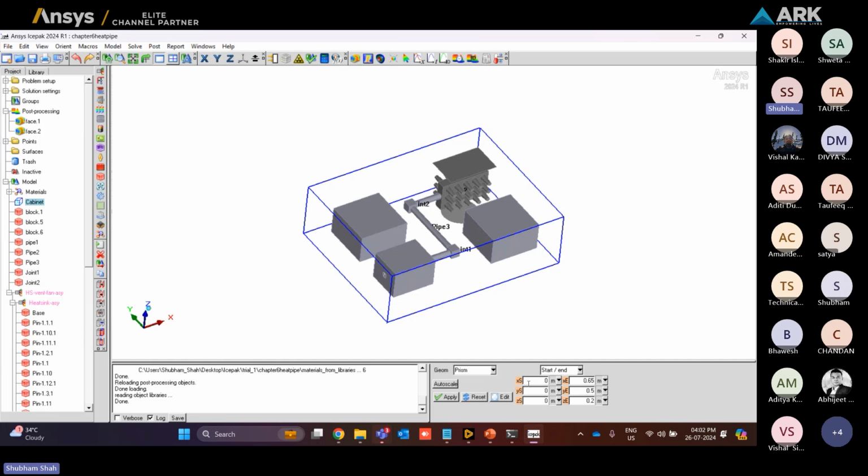That is basically XS, XE. So what this XS and XE indicates is X in the axis is X-axis and the start point is 0 meters and the end point on X-axis is 0.65 meters. So this is how it will create your line or cube in the X, Y, and Z regions. You can define whether you want to go with the prism or other options. This is basically already prismatic type of geometry, so that is already a prismatic option is available.